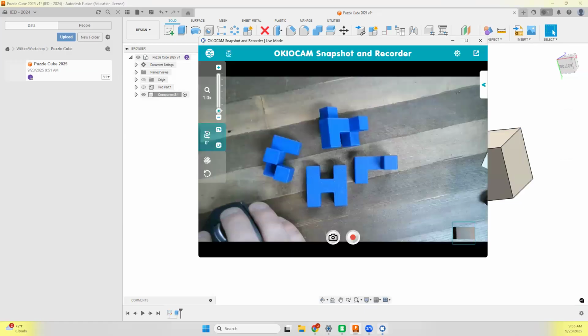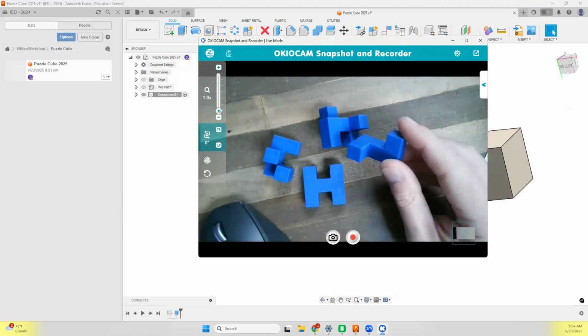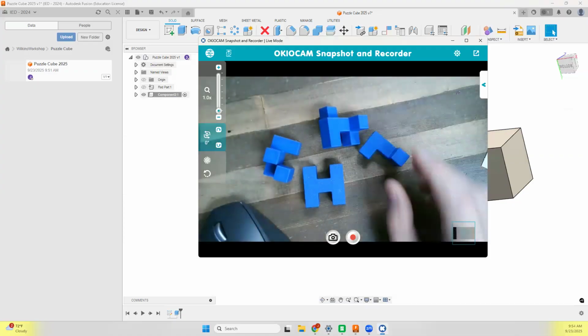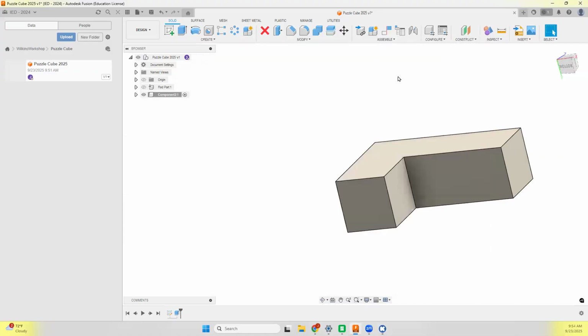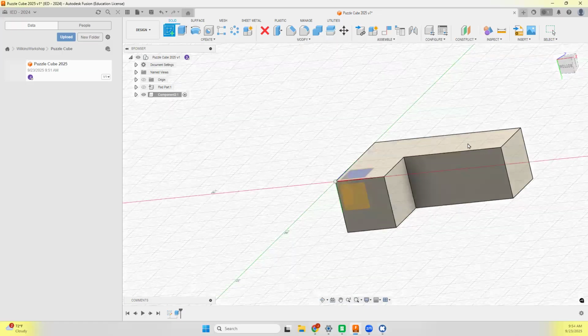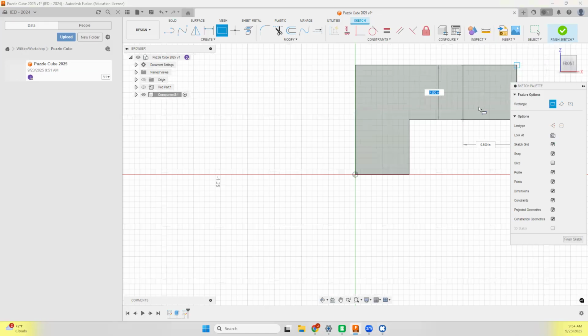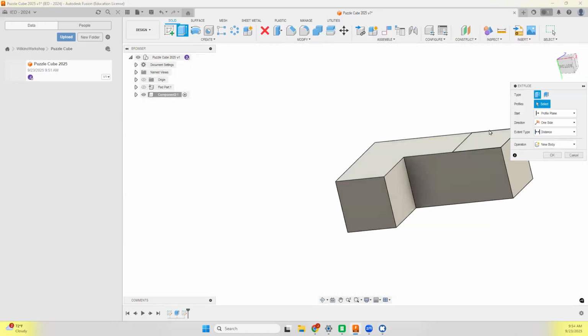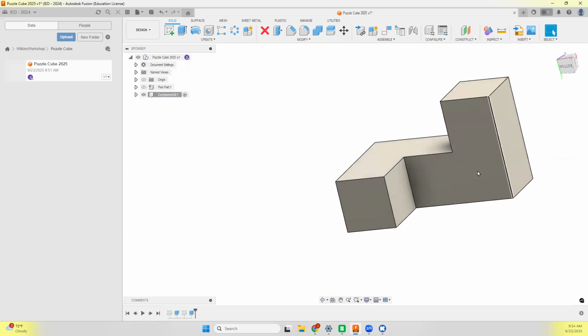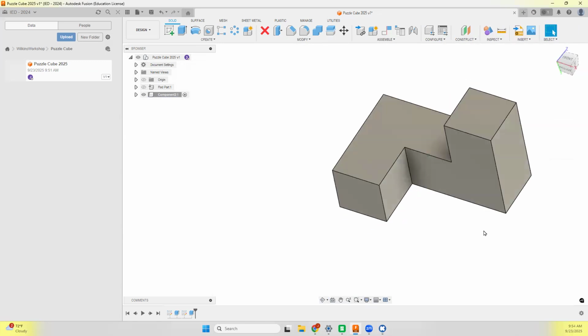And if we look, so I just did kind of the base of that, and I'm going to extrude that square upward. So I'll do a new sketch on the top surface here. Go rectangle from that midpoint to here. Don't even have to dimension any of that. E for extrude, 0.5, and there's our second piece. We'll call this one blue part.